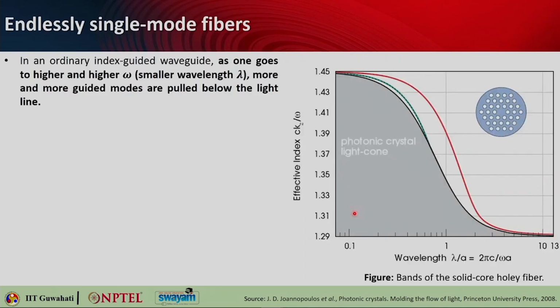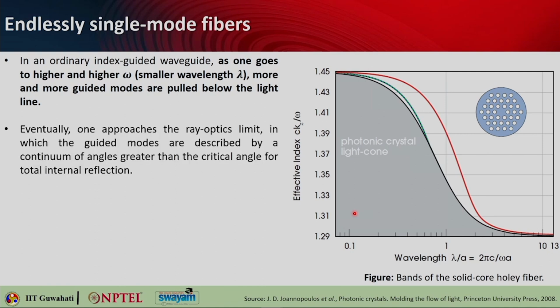Now in an ordinary index guided fiber, one can go up to higher and higher frequencies, or smaller wavelengths, and more guided modes can be pulled below the light line. So higher order modes are also possible.